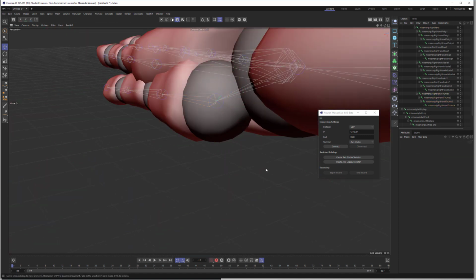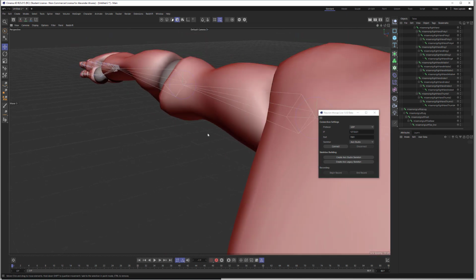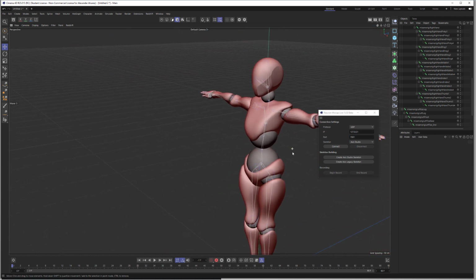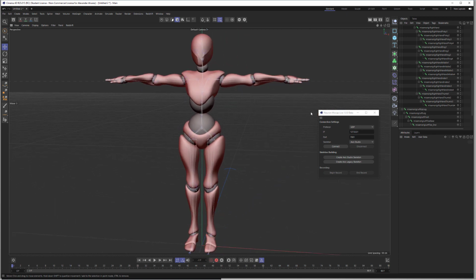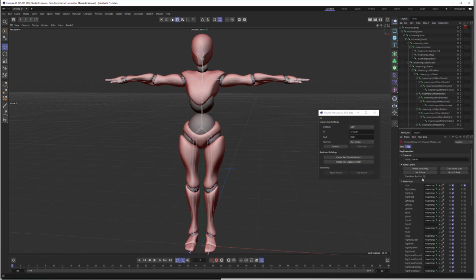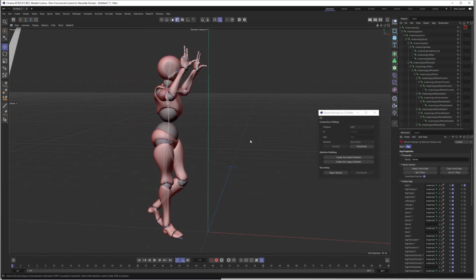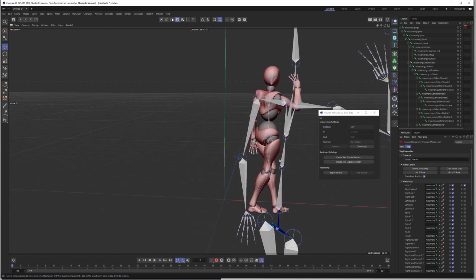And now our character T-pose has been corrected. Once it has been corrected, we're going to inspect everything, make sure that our character is following this T-pose that was required for Access Studio. We'll go ahead and select the tag again. And now we're going to set the T-pose. We'll see that now we have a little T letter next to the bone, and we need to scale the root position. Once that is done, now we can click on connect, and we'll see that our character is now receiving data from Access Studio.